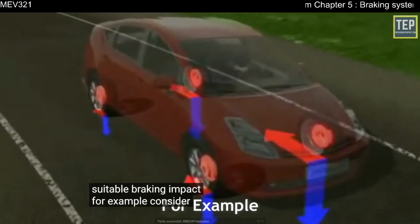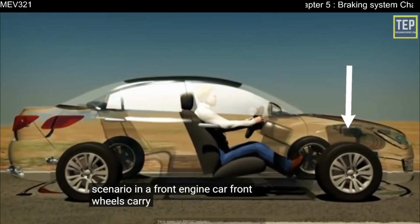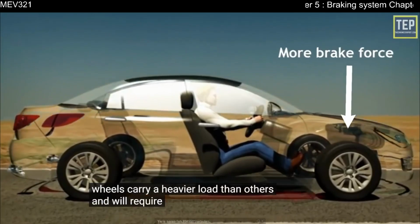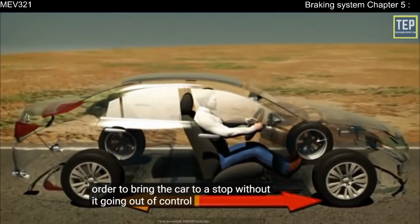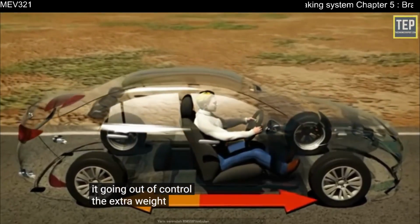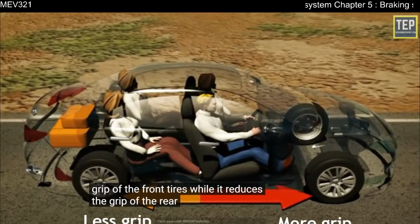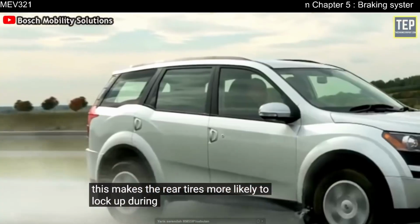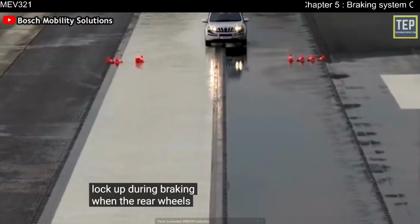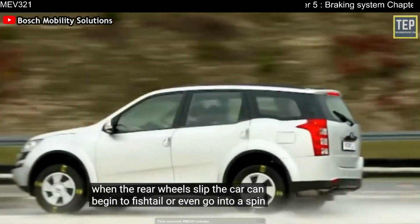For example, consider the most common scenario. In a front-engine car, front wheels carry a heavier load than others, and will require more brake force in order to bring the car to a stop without it going out of control. The extra weight up front increases the grip of the front tires, while it reduces the grip of the rear tires. This makes the rear tires more likely to lock up during braking. When the rear wheels slip, the car can begin to fishtail or even go into a spin.